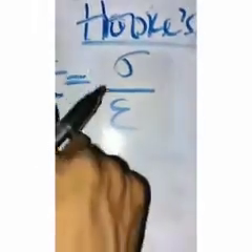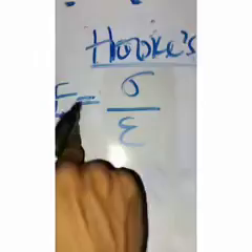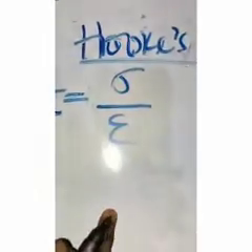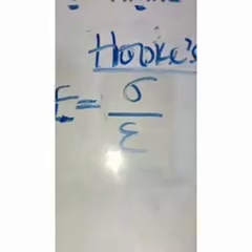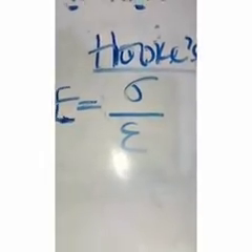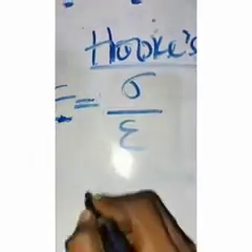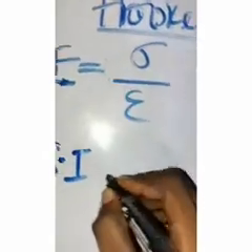Now this Young modulus, it's very important you know this law. The Young modulus E is defined as the simple tensile or compressive stress within elastic limits required to produce unit strain. I say again, the Young modulus may be defined as the simple tensile or compressive stress within elastic limits required to produce unit strain, and the unit of E is kilogram per centimeter square. Otherwise, if you are given a question, you will change this centimeter square to meter.